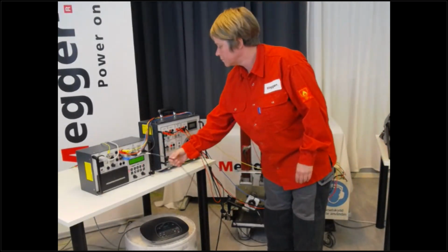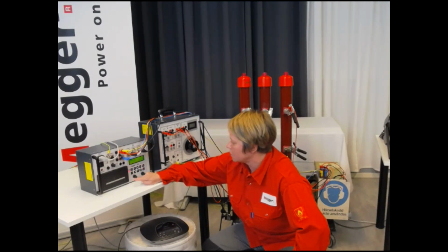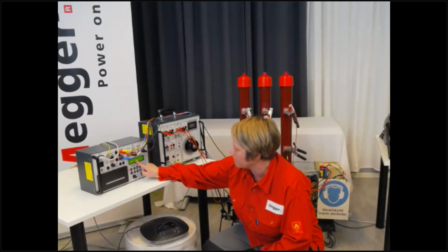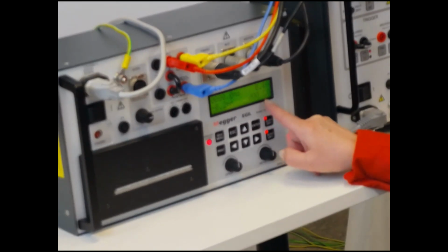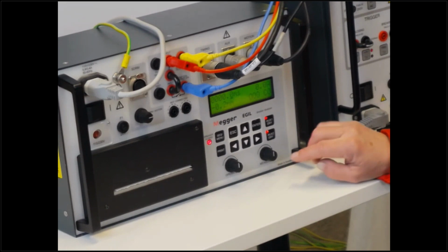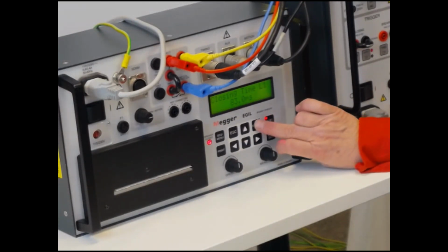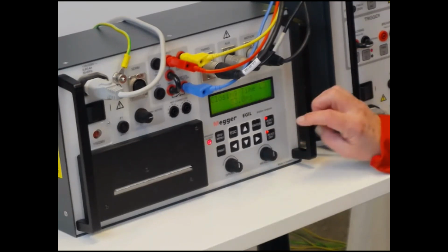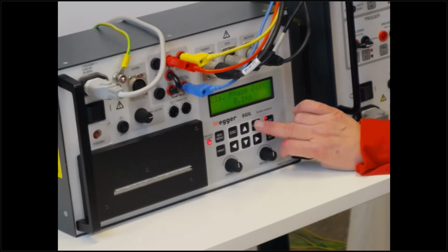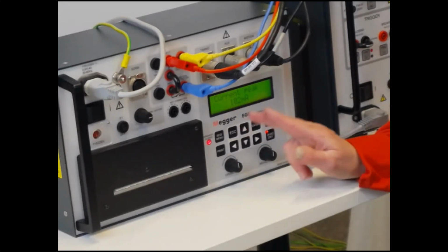It needs a little time. And I need to go to the display here. In the main menu, you have a display. The result is that now the breaker is open and the first auxiliary contact is closed. So that is as expected. And if I go down one more step, I can see that the close time was 83 milliseconds. And for L2, it was 82.9 and 83 for L3. So A, B, and C phase are very, very similar, as expected. A difference of 0.1 milliseconds. The current peak is as low as 102 milliamps, so it is consuming a very small current.